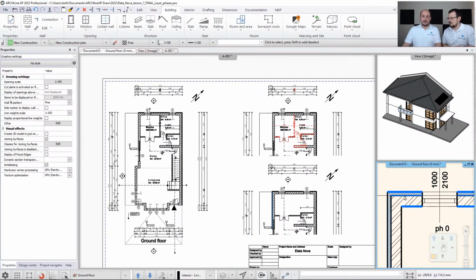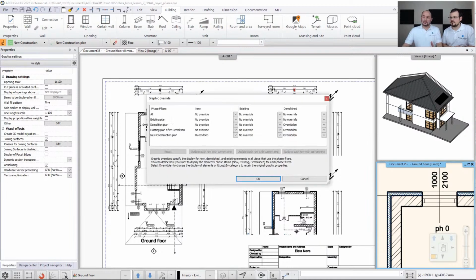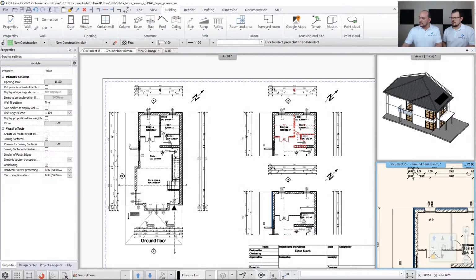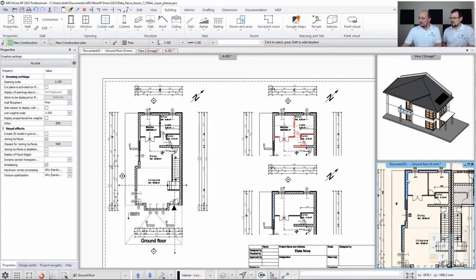It is recolored because you have an override option. The software is shipped with default settings, but I changed it with this override setting to represent anything that appears new in blue on my drawing, because the things that are demolished are red, as you will see on the design. After that, I made a copy of the properties using the copy properties command on the rest of these items.